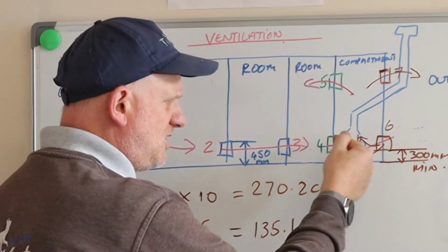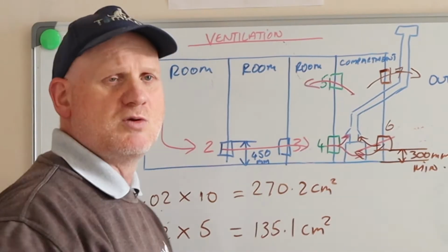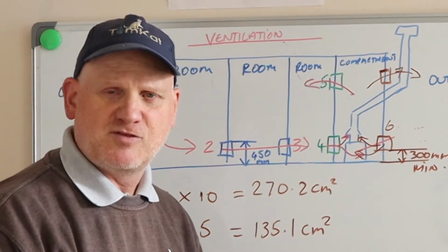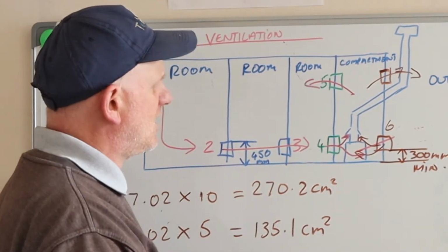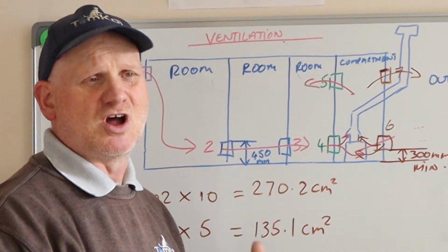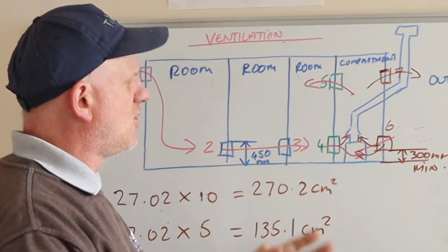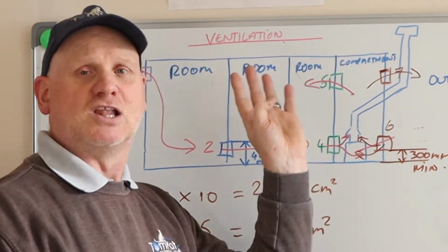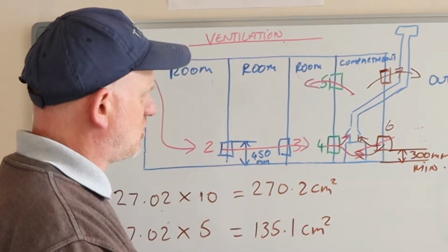So if we did do this, the air from outside would go straight through, straight into the room and not give us our air for combustion. This is called cross ventilation and this is not allowed. This would also be deemed as at risk in an unsafe situation. So they have to be on the same wall, high and low, communicating from the same direction.